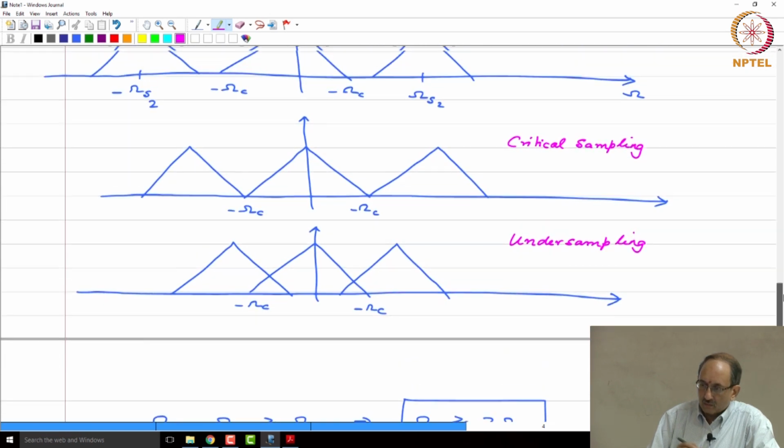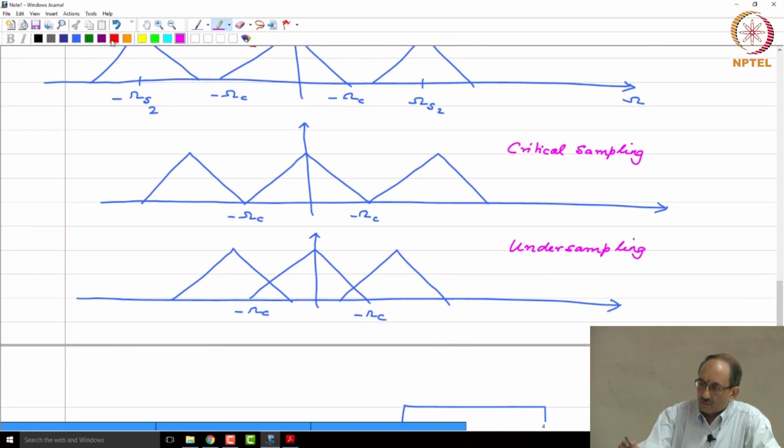And yes, question. So why do we care about low pass band limited, even if it is band limited around some higher frequency? Even then we get repetition similar. Yes. So what will happen when the signal is band pass? There also, as you rightly say, there will be repetitions, and then you can come up with a version of the sampling theorem such that the sampling frequency required is not twice the highest frequency.